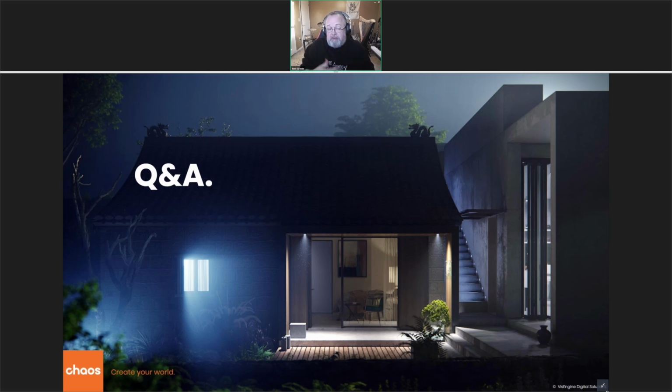objects. And then the only thing left for you to do is pick the distribute on object that you want the scatter to apply to, because obviously we can't give you the distribute on, that's dependent on your scene. So yeah, the scatter preset contains the scatter settings and all the models that will get scattered. I actually find that super handy. It's not hard to set up a scatter, but having a preset to get you started that brings in the models and some good settings is just making something easy even easier.